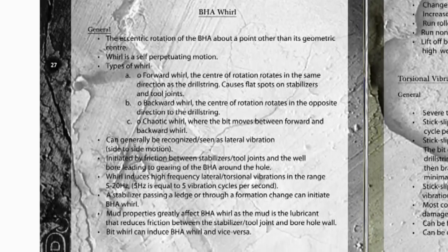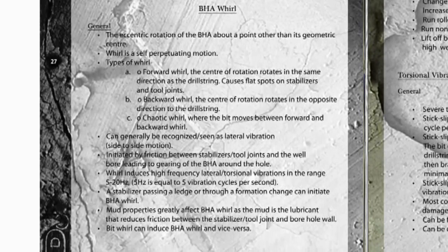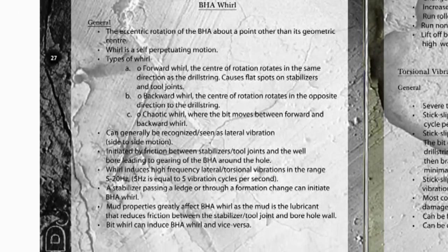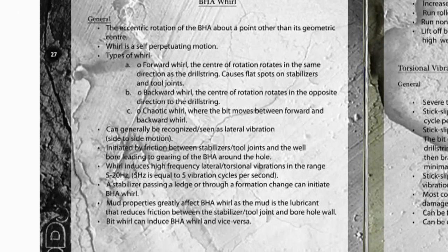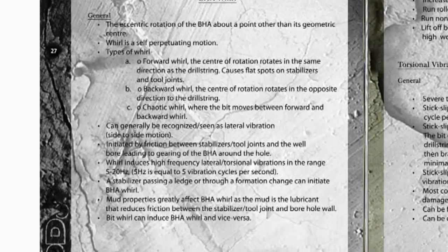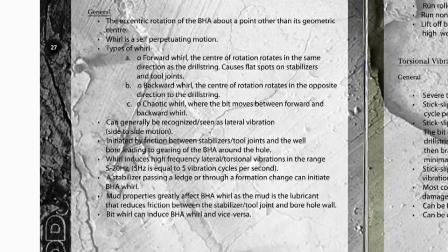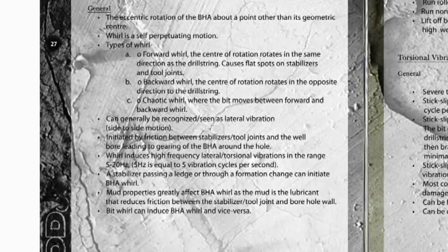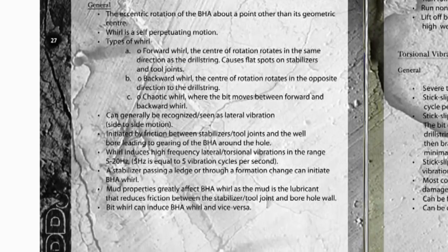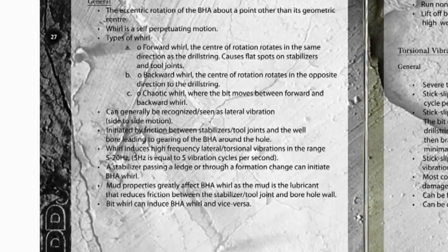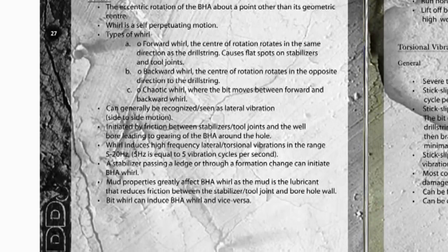A stabilizer passing a ledge or through a formation change can initiate BHA whirl. Mud properties greatly affect BHA whirl, as the mud is the lubricant that reduces friction between the stabilizer or tool joint and borehole wall. Bit whirl can induce BHA whirl and vice versa.